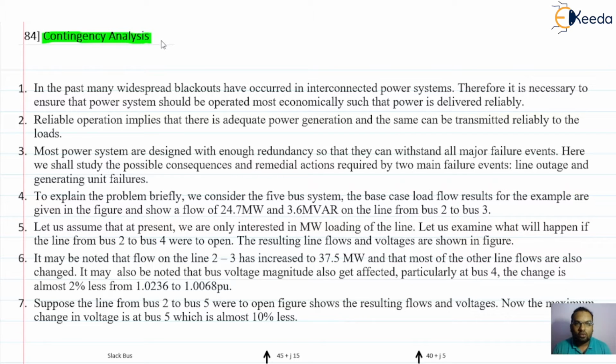We have discussed how to model the power system for the contingency analysis. As per the requirement, we can model the power system in different ways, taking the help of the Newton-Raphson load flow method, or the decoupled load flow method, or in some cases the fast decoupled load flow method as well. Again, during the security analysis we discussed the three major functions of the contingency analysis.